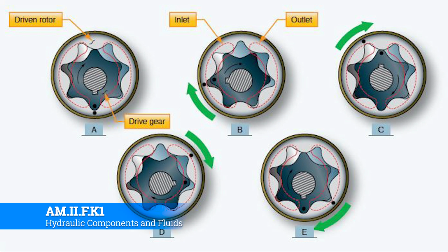Anyways, in a gerotor pump, you have a fixed housing, and then you have that single sprocket that goes around and does all these things. Now, the reason we want to know this is so we can troubleshoot just like we did with the drive gear pump. It's not to just fill your head with useless knowledge. It's actually there for troubleshooting purposes. If you understand that it's a gerotor type pump, or a gear driven pump, or a centrifugal pump, or whatever, you can understand how it works and why it works, and extrapolate the effects it's going to have on the greater system.